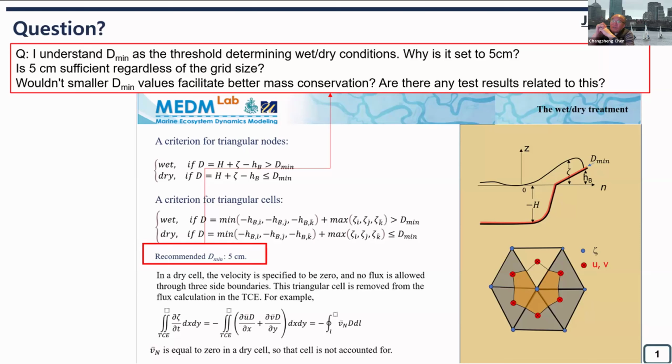But then you look at all other models, including FVCOM, ROMS, and MITgcm, we only specify the bottom stress, right? We specify the bottom stress in the lowest layer. We did not resolve the whisk layer, so we consider the whisk layer through the bottom roughness. How large the bottom roughness is, is determined by the log layer at the bottom. We assume the log layer, the constant stress layer, to determine what the CD is.